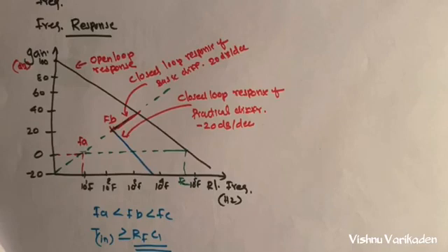If you increase the frequency to a very large value, stability and noise problems happen in the basic differentiator. So we change to a practical differentiator by adding two components, one resistor in series with the input, and one capacitor in parallel with the feedback element.